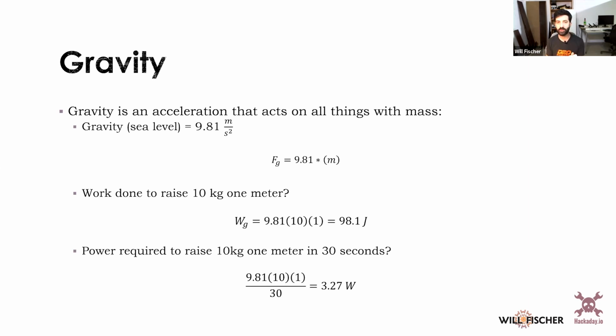Like, I've spent less than 30 seconds so far on this slide. It is creeping up there, right? So you can use a relatively small motor to move a lot of weight, potentially. And that's why I'm talking about this stuff now, is when we think about how we size our motors later on, we'll want to think about that in terms of watts. And so you want to figure out the job you have to do and then spec your motor accordingly. So that's why we're talking about all this math now.